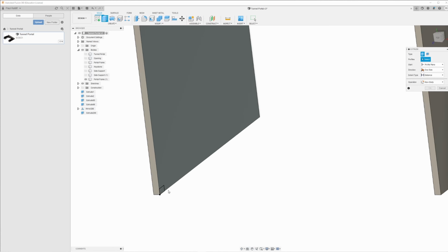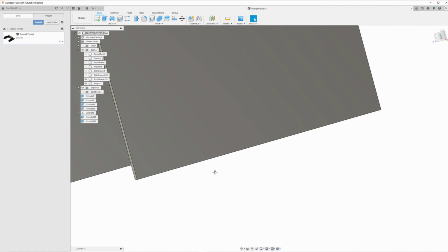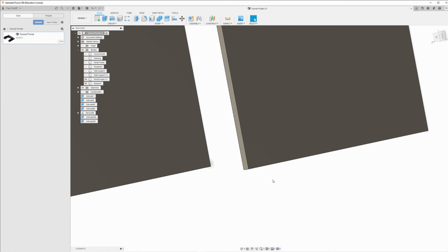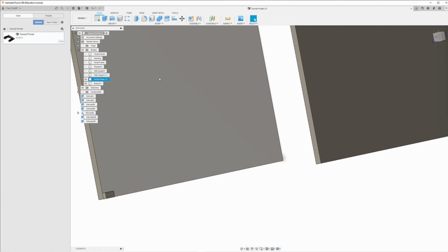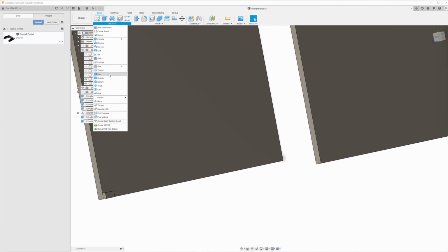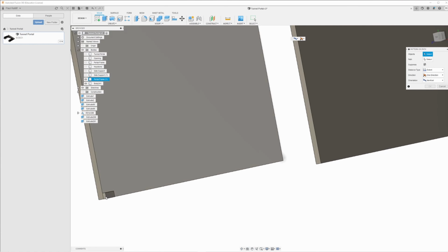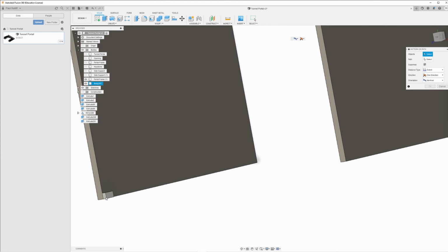E for extrude, we'll select that. 0.06, and as always a new body. Okay. And yes, we are going to create another path. So create pattern on path, select our new brick as our object, and as always make sure you select the entire object, not just a face.